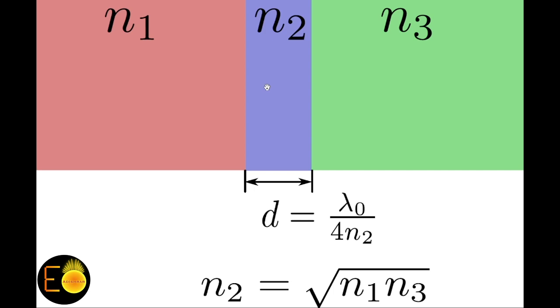In order to do such an experiment, I need to make two types of parameter study. The first one is that the parent sweep will be the variation of the dimension, and the child sweep will be the variation of the angle, from less than 0 degrees to greater than 0 degrees. But one more thing we have to keep in mind is that while I am decreasing the dimension of the middle layer, the other two layers will automatically be adjusted accordingly. While I am increasing the width of the middle layer, the other two layers will also automatically be adjusted. So we have to keep these things in mind.